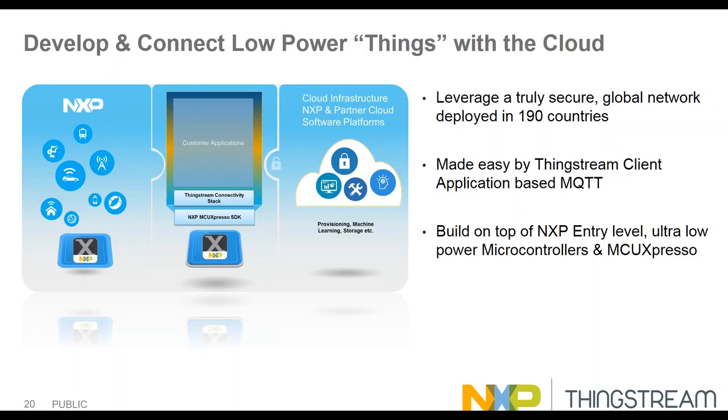If you're already connected to the cellular network and you send a message on ThingStream, you can expect that message to be sent and received at the other end in under a second. So it's relatively quick. It partly also depends on the size of the message. Individual USSD messages are basically 160 bytes in size, but that complexity is hidden from you by the SDK. If you choose to pass in a message of 4K, for example, it will send and receive multiple messages and acknowledgements backwards and forwards between the server without you noticing. You don't have to worry about breaking up your payload packets. The SDK fixes all that for you.